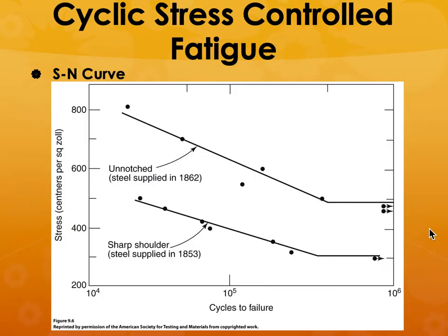Okay, now how do you represent that for engineering design applications? You plot the cycles to failure versus the applied stress levels, and you determine the cycles to failure for each stress level, and you plot that.